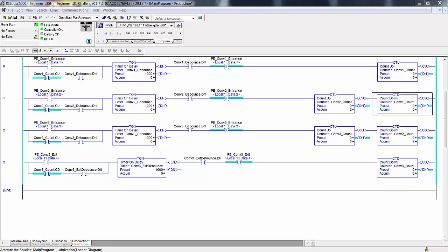Obviously in step 8, you could run conveyor 1, but you know what's going to happen? If you're not running conveyor 2, then that carton in the lead will just push up against and maybe a little further up onto conveyor 2, and then it'll start slipping on conveyor 1, and then all the cartons behind it will catch up, and the 4th carton, the one that's coming on now, step 8, won't clear the photo eye. It'll never clear the photo eye without running conveyor 2.